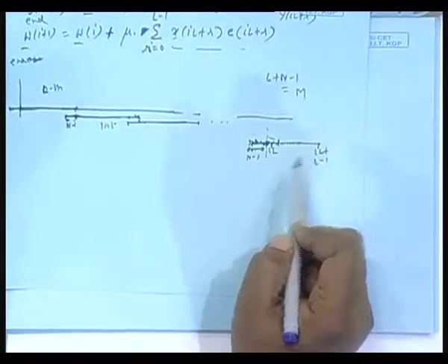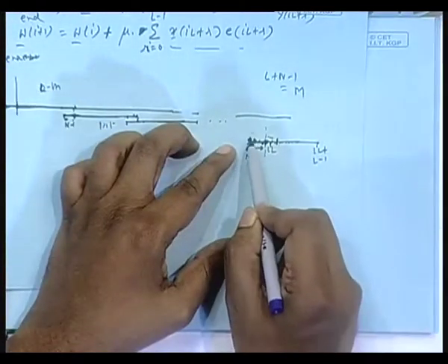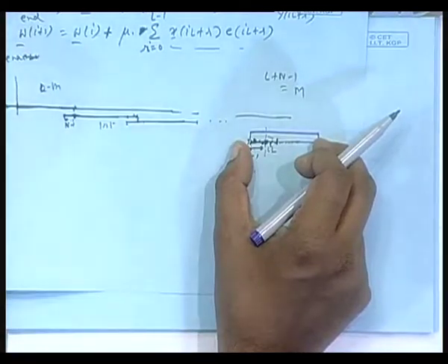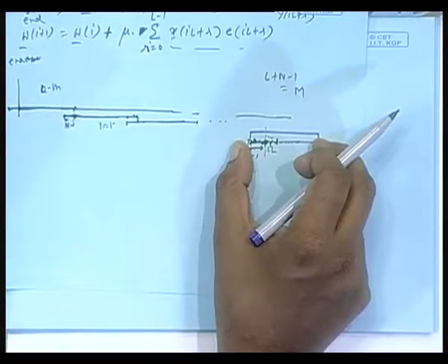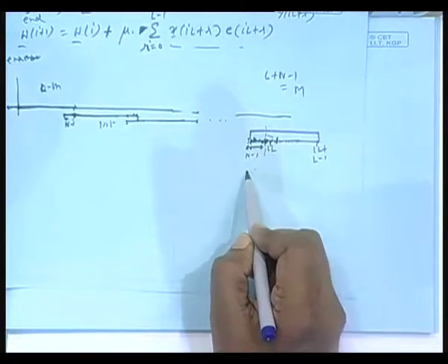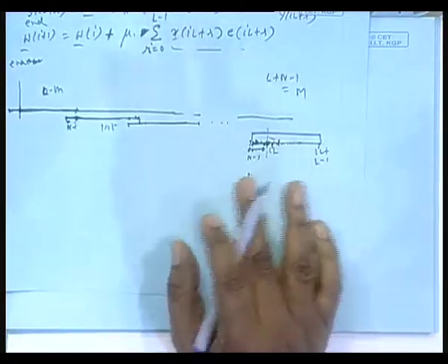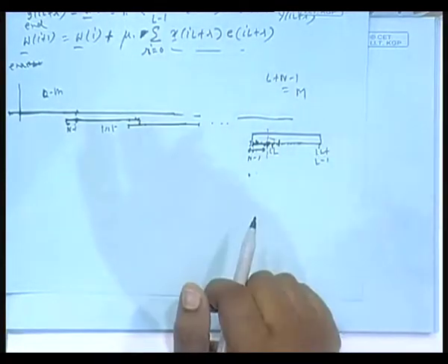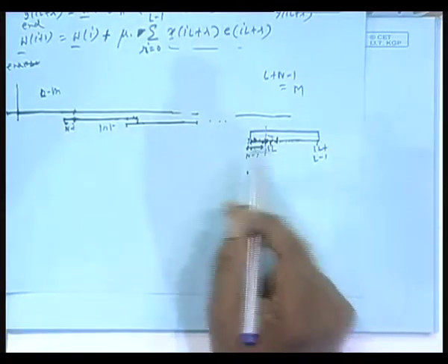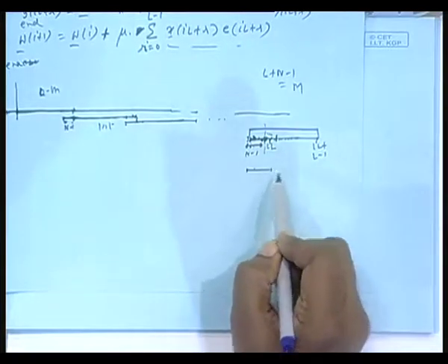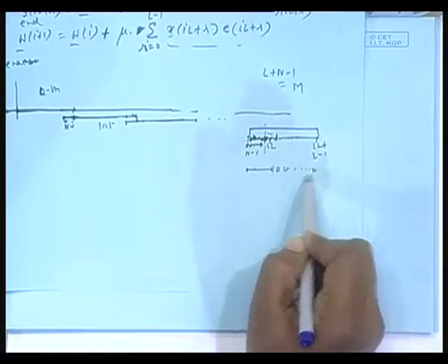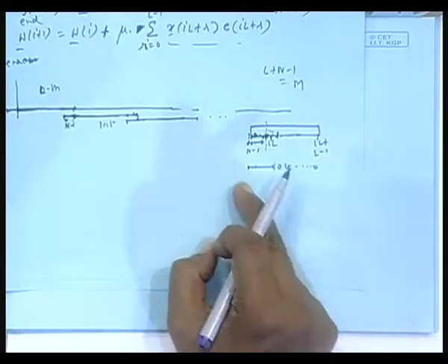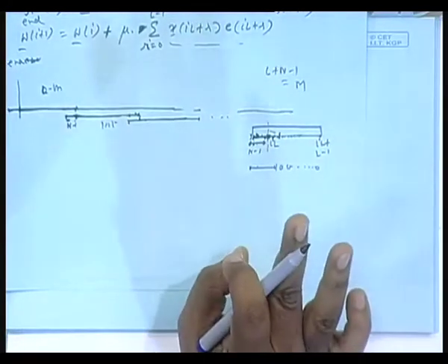For the filtering part, what will you do? For this block, I took the DFT of this. Are you okay? And filter weight, suppose I know the filter weight has been updated, I know the filter weight for this block, ith block, Wi is known. How we do the convolution? Wi here, and then you have 0, 0, 0, 0, 0, isn't it? Then two lengths are equal, then do circular convolution, ignore the first n minus 1, remaining ones are correct.